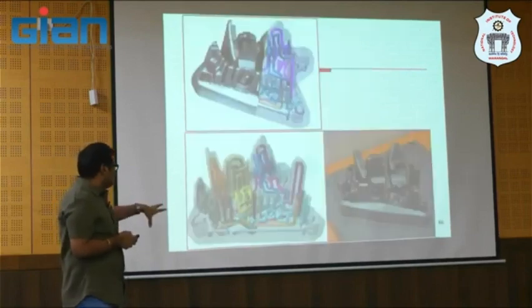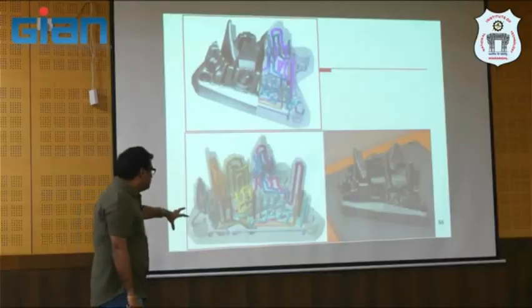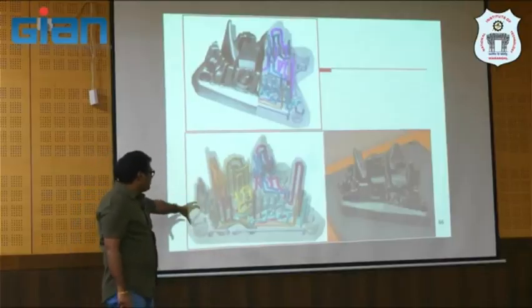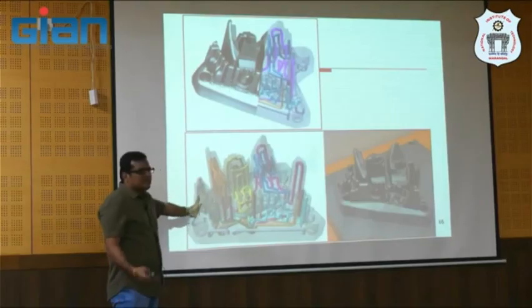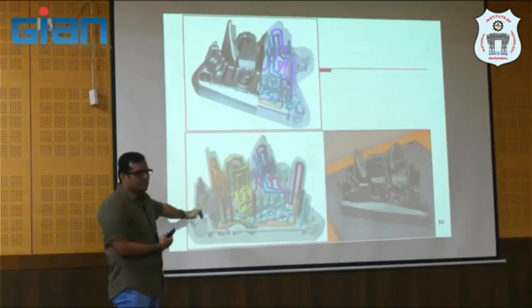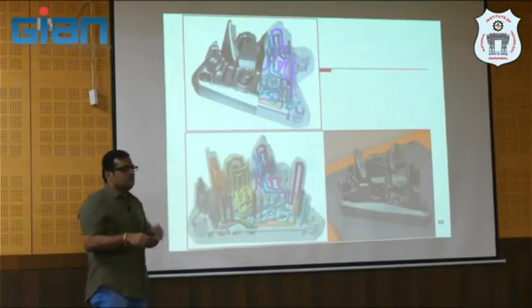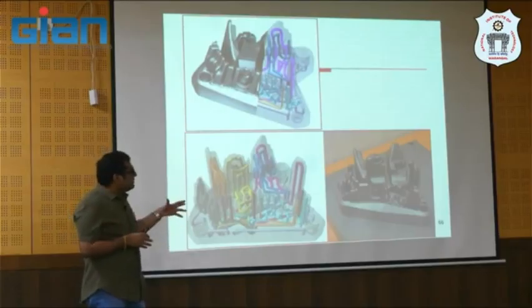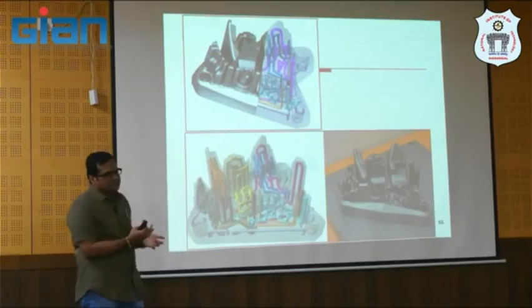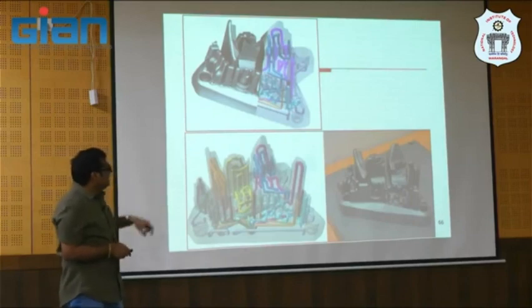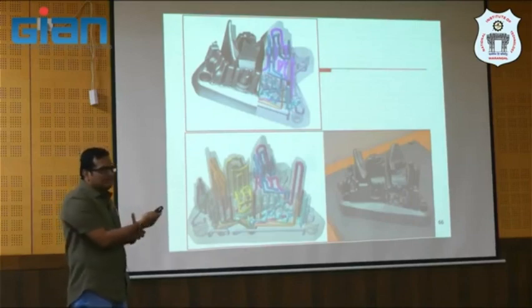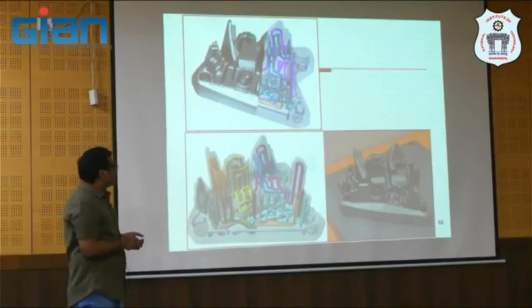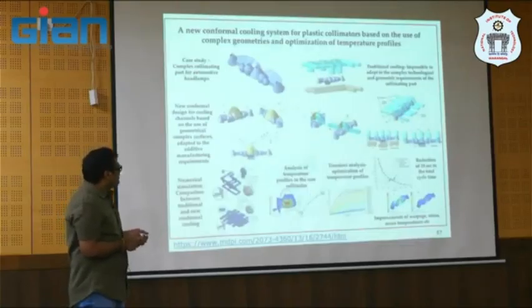Yeah, you see here, this is the conformal cooling channel where the cooling channel has been an integral part of your tool in a single setup. You can complete this. You just design a tool with the integral cooling channel, right? And with your powder bed system, you can print powder to tool in a single setup, right? So you can do all that simulation, design your tool, and then print it. And these are some of the case studies.